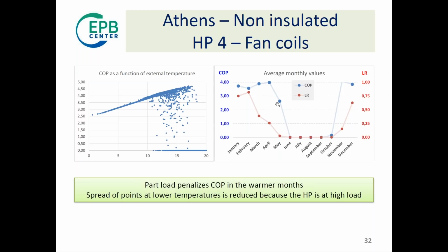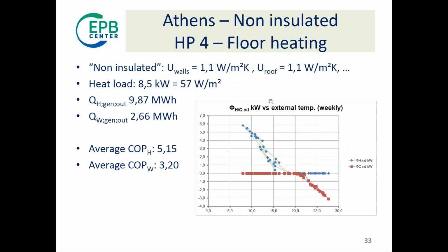It's not really such a disaster, because here we are speaking of a small amount of energy that will be produced with a low COP. So the most important thing is really the part here. But nevertheless, don't oversize your heat pump, because you will have a lower efficiency. So here for comparison, I did the same calculation for a floor heating, so same results. And here you can see in our graph that the cooling part is appearing, but that's not the question today.